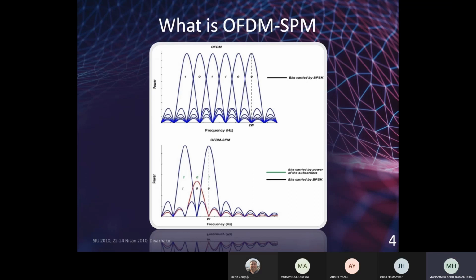In this figure, here is an example of OFDM-SPM paired with QPSK modulation. In the original case, OFDM works with subcarriers back to back, and each subcarrier carries a data symbol. So for example, in a quadrature component or an in-phase component, when we carry these 6 data samples, we carry them in only half the bandwidth and also half the power. So in OFDM-SPM, we send the same amount of data using half of the power, half of the latency, and half of the complexity.